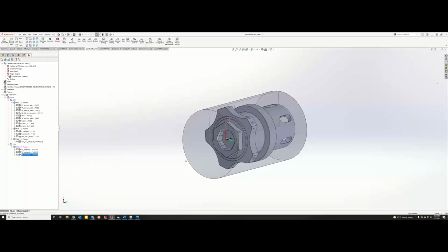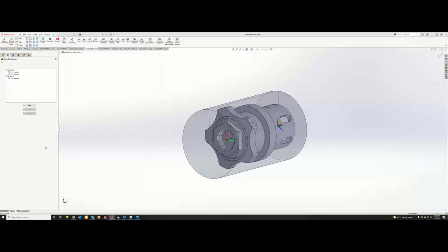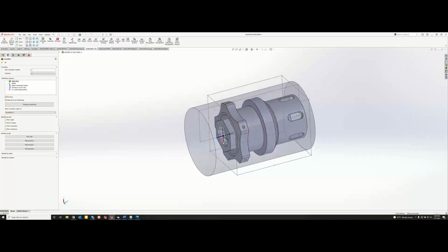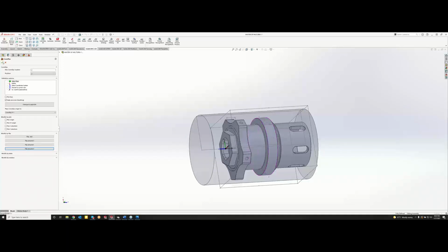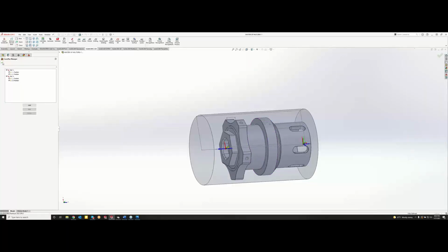Now I'm going to start our milling process, and I'm actually going to do just an iMachining operation for this one. I'm going to come to my Mac 2 position 1 and click my coordinate system button. Now I need to add a Mac 2 position 2 for my sub spindle, but with my Z going out. So I can tell it to go off of my coordinate system 2, with my Z pointing out, and I'm just going to do a quick flip around to get everything lined up again. I'll go ahead and accept that.